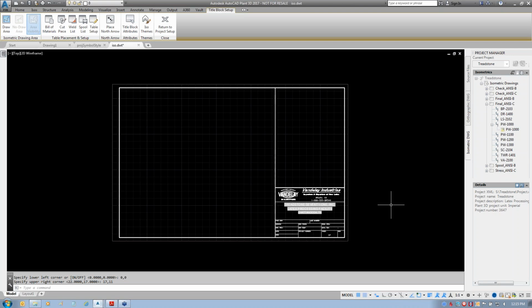A couple of settings I personally don't want. This is where you would set it. If you have things you don't like to see in a drawing when it's created, if you want to set it here, such as units and things like that, you need to take care of all that in the template, because that's what I'm working in right now, the ISO template.